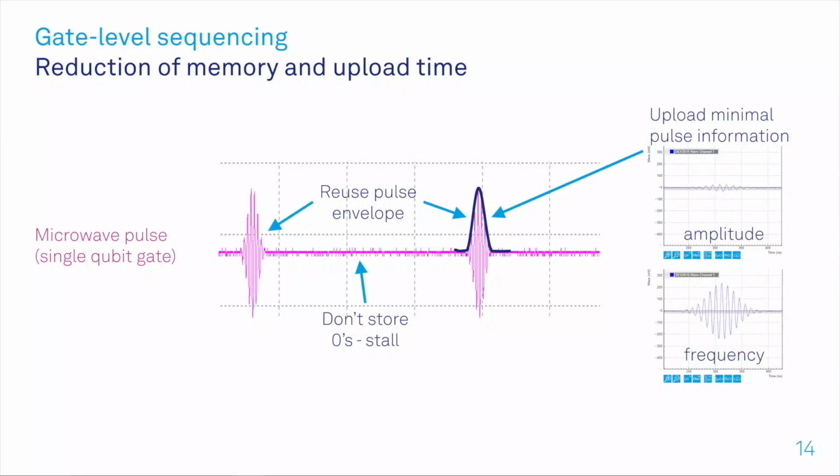Good, so now we programmed a simple Ramsey sequence with 2 Gaussian pulses, but there's one key ingredient missing, and that's the frequency. Especially for microwave pulses, we often use IQ up conversion to convert a pulse at an intermediate frequency of, say, 100 megahertz to microwave frequencies at, for example, 6 gigahertz using a local oscillator. That way, we gain control over the phase, frequency, and the amplitude. For this, what we need to generate are 2 pulses with a phase difference of about 90 degrees and a frequency of 100 megahertz. What are our options?